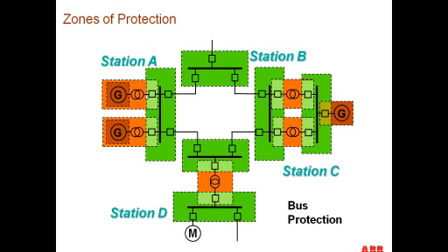CTs that are on the generator side of the breaker and for the bus protection. So we include the whole bus plus the circuit breakers in the protected zone by using CTs on the opposite side of the scheme. Now we look at line protection. Your line protection overlaps the bus protection by using the CTs on the bus side of the line, so we get overlapping protection of these breakers again.